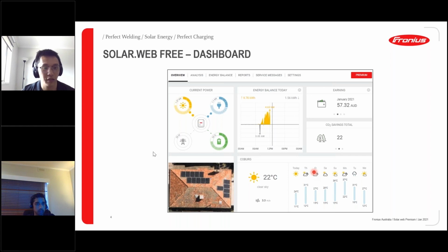Good question here. Can we update firmware for batteries using SolarWeb as we can for the DM card and the inverter? So with this one, you can't update. Like for any inverter, you can't update the batteries. Usually, right now the possibility is with BYD. And if you have a BYD battery, you need to use the app to update the battery, so you can't do it via SolarWeb.